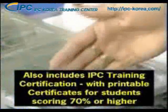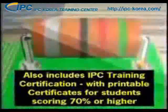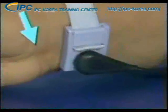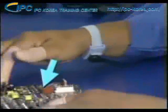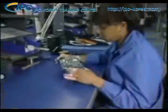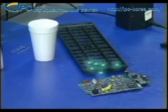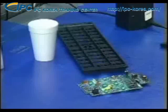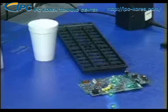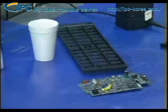The third material is called partially conductive. Materials that are partially conductive fall somewhere in between conductors and insulators. They are conductors, but not very good conductors. The human body, most electronic components, and static dissipative materials are classed as partially conductive. They will allow grounding techniques to be used, but electrical charges are drained slowly. This is actually a desired feature in many cases, since draining charges slowly minimizes the chance of damaging electronic components.